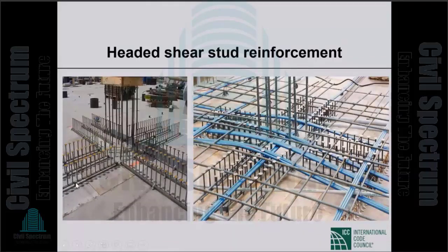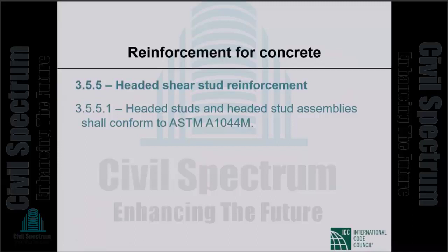So there is a rail, a strip of metal with those studs welded to the metal strip. The head of the stud is much bigger than in the typical Nelson studs. These are big heads which anchor the studs to the concrete, and if properly anchored, those legs of the studs resist shear. Okay, so this is now by far the most popular punching shear reinforcement throughout the United States and in many countries of the world.